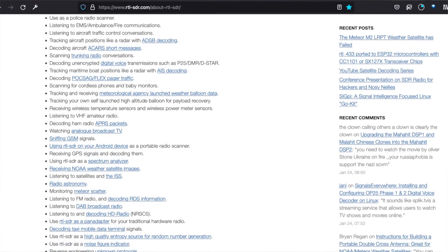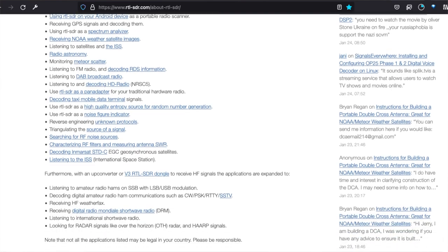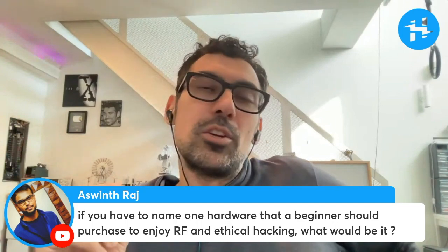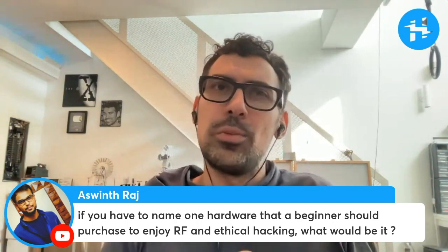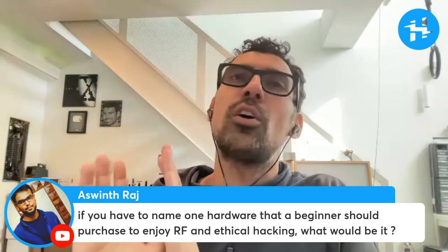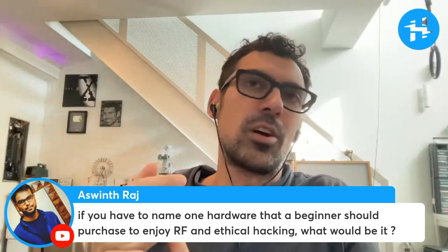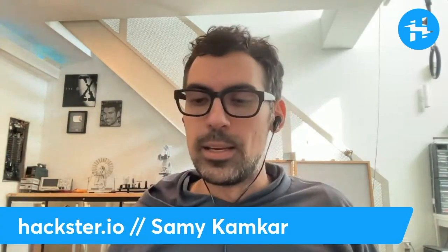So it would basically sniff the UHF, ultra high frequency TV signals from the air and then run it through your computer. But your computer's software did the decoding. So someone figured out that it was actually the software doing the decoding, not the hardware. And all the hardware was doing was sampling the RF and then sending it as what are called IQ samples, which is really just the amplitude and the phase.